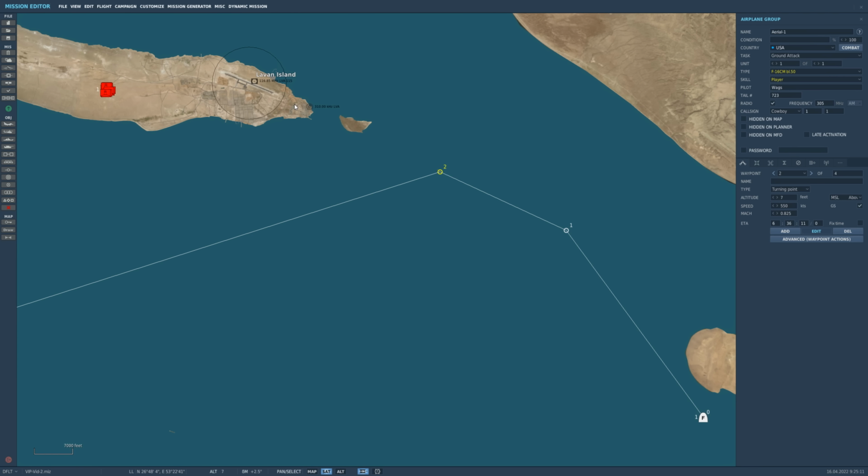So as we talked about at the start, any steer point can have an OA1 or an OA2, which we talked about in a previous video, as well as a VIP or a VRP. And in this case, what we're going to be doing is assigning steer point 2 with a VIP. So steer point 2 is going to be the IP, initial point, and from that, we can find a target point based on a range and bearing from it.